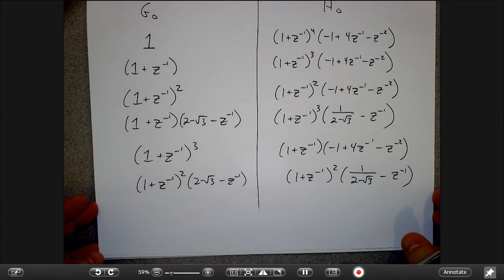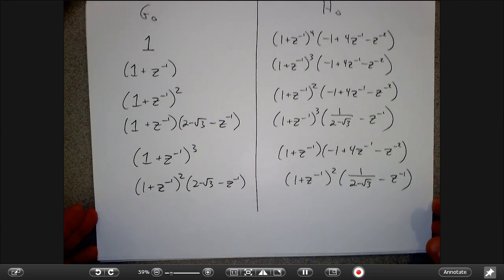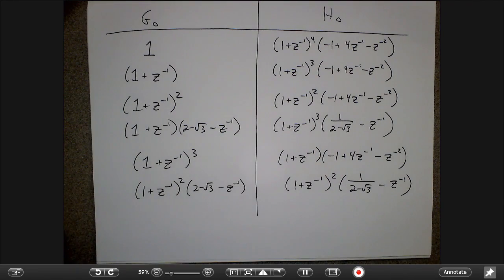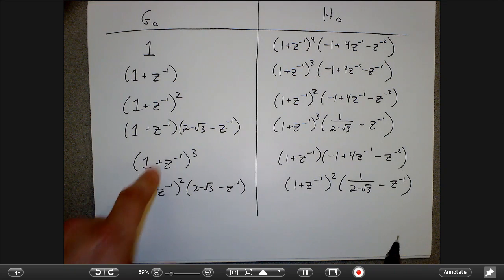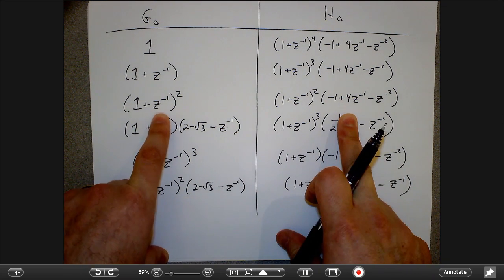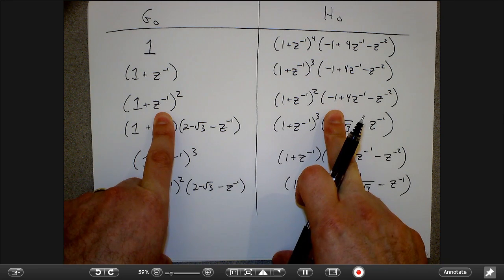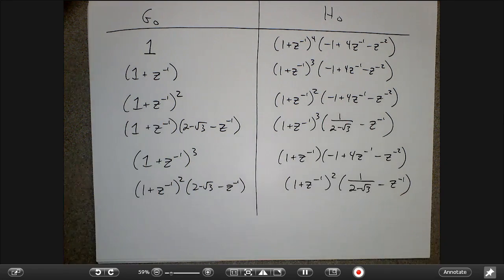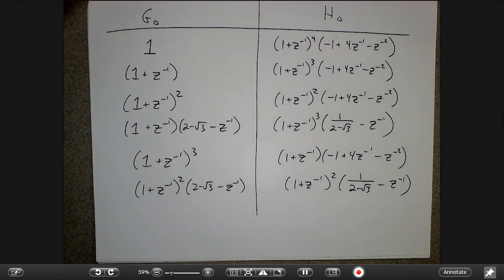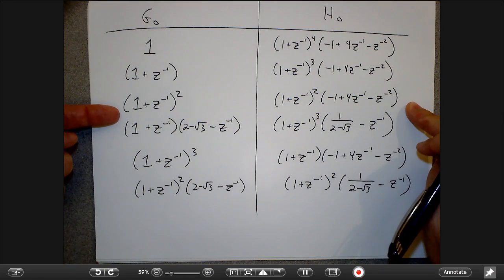And so why would I want to do one or the other of these kinds of options? Well, for example, this one is kind of nice, because both these filters are symmetric. That means that they have linear phase, and we already talked about in FIR filter design that linear phase was good, right? So both of these have this nice symmetric-around-the-middle-tap property. So that might be something that would be nice.